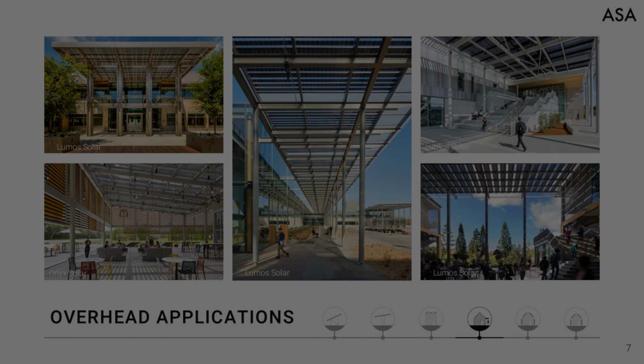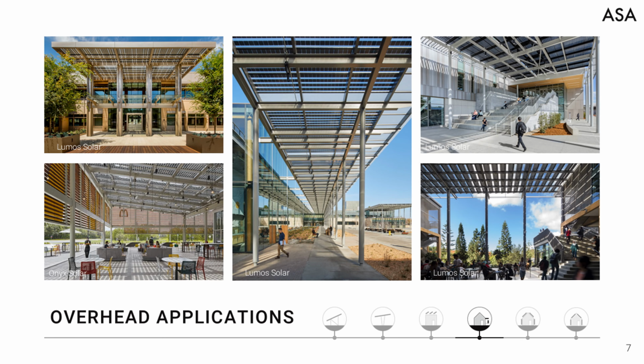Next, I would like to dig into how slope glazing requirements can play a role in standard photovoltaic installations. The International Building Code, Section 2405, is devoted to slope glazing and skylights. Overhead solar, as seen here, would fall into this classification. Section 2405.2 discusses allowable glazing materials and states that as long as laminated glass is utilized with a PVB or equivalent interlayer, screens are not required under sloped glazing.